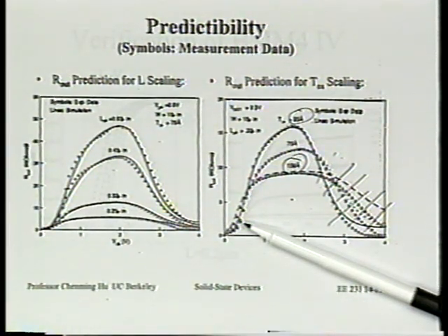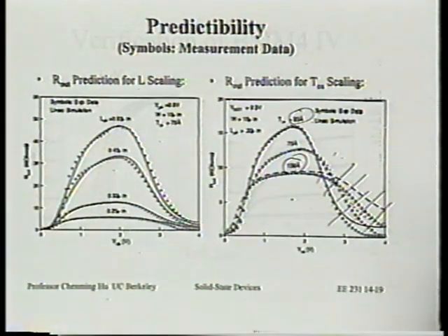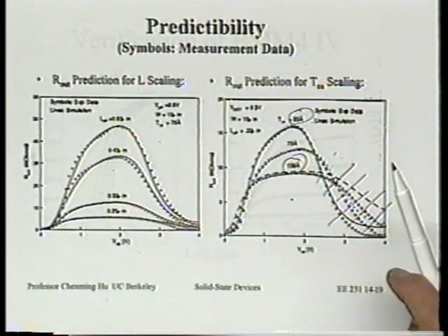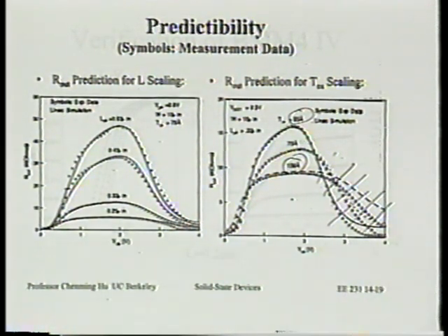Well, I actually have a question if you can explain it. Is that VGST, that's VGS minus VT0, or minus the VT associated with the channel length? Minus VT associated with channel length. All right. Okay. Back to this discussion here. It's a very interesting comment that in the thin oxide, by the way, it's correct, the DIBL factors into this.